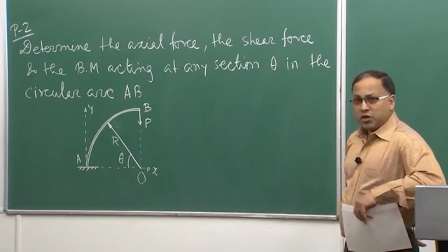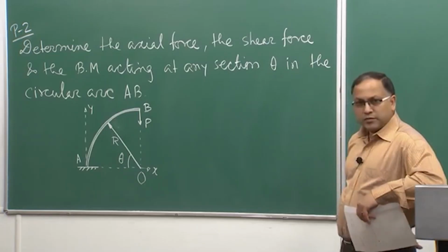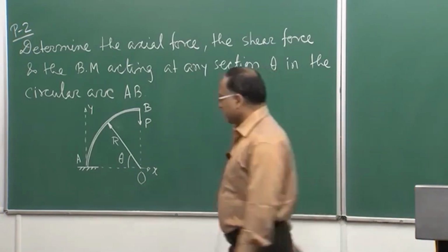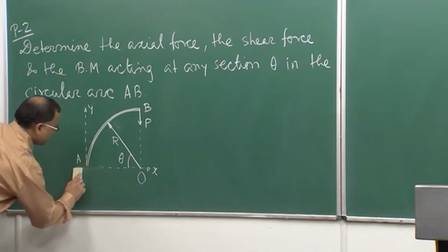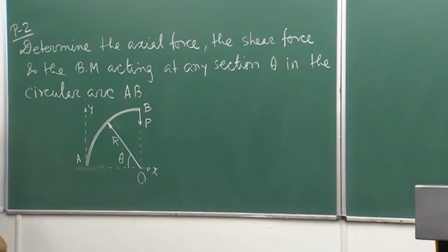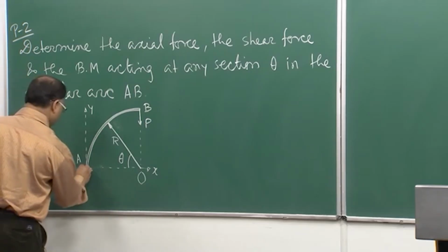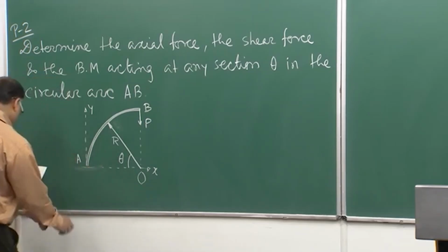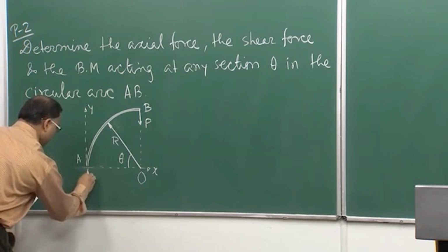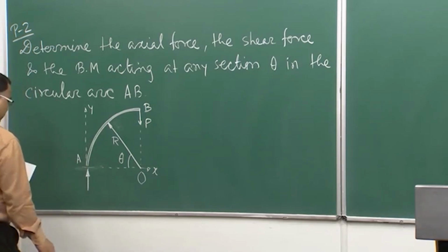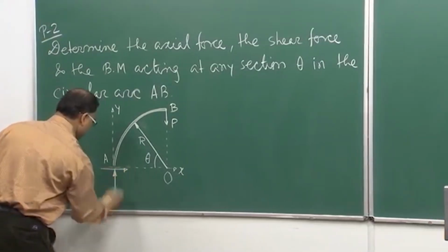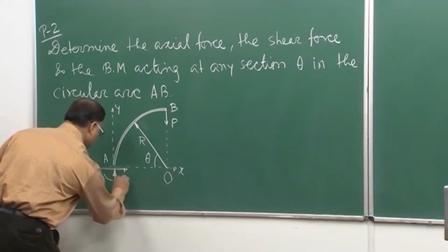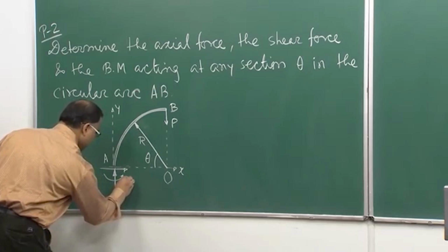So, what is my first job? If we want to solve this problem, what is my first job? First job is to draw the free body diagram. So, let us draw the free body diagram. We will remove this support and replace it by applying the forces: y direction force, x direction force and moment.